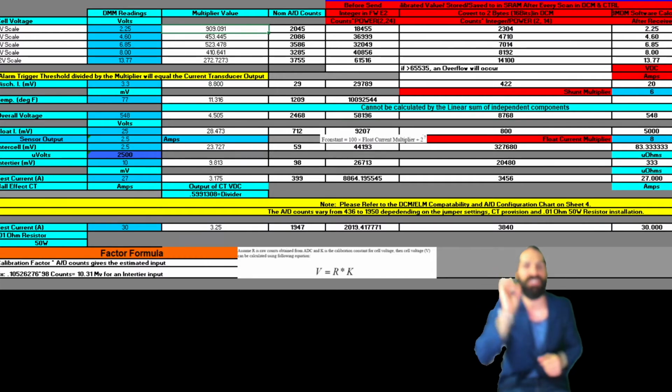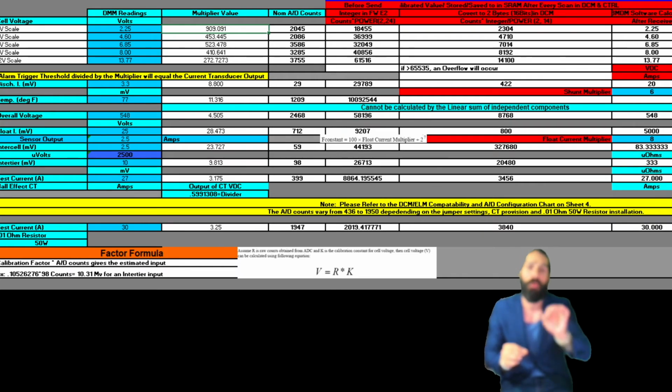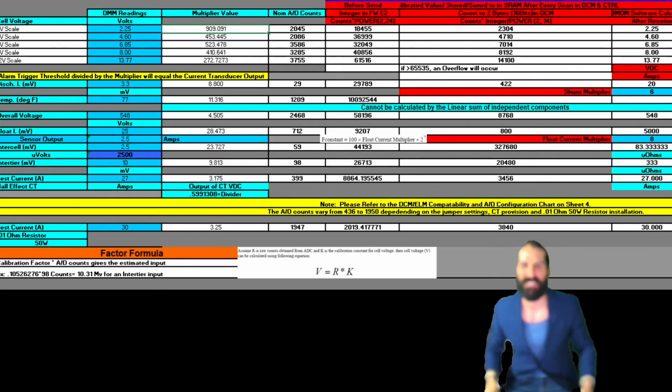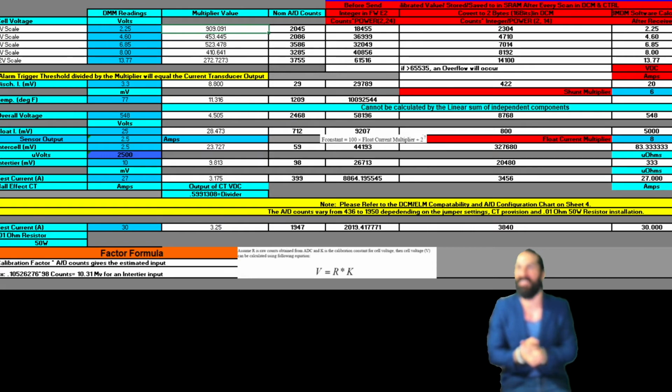This is why it's so important that every single monitoring system has an annual recalibration. It's difficult for me to comprehend and fathom that all of these data center managers treat UPS systems so critically, but the battery monitoring system is literally monitoring the heart of the power system. Without the battery, the UPS is a glorified power conditioner. It's almost worthless, right? So all the monitoring systems should receive much more attention than they currently receive.